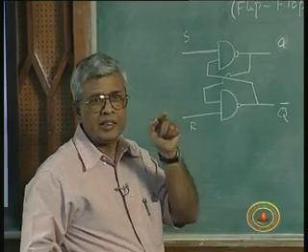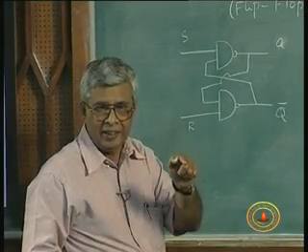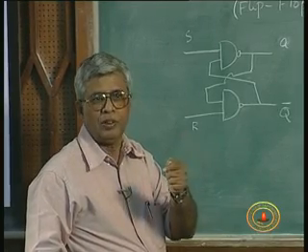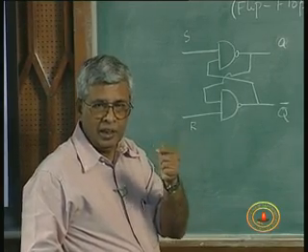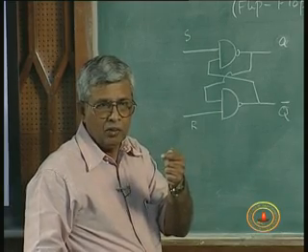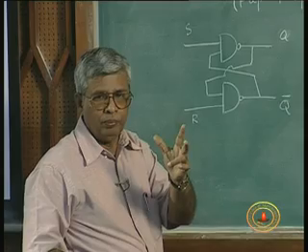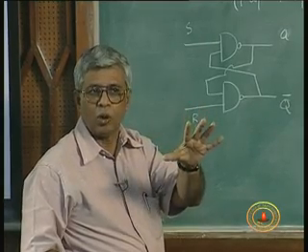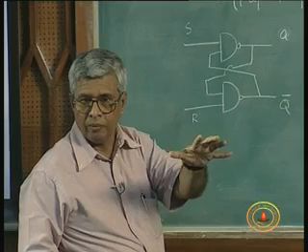Only when the gating signal is enabled or the gating signal is high, whatever the S and R combination, the output will change accordingly. If the gating signal is not enabled, whatever values you give to the inputs, it does not affect what is already stored, it will remain as a memory state.